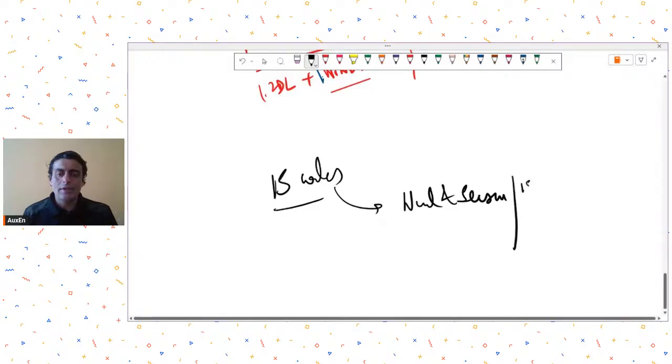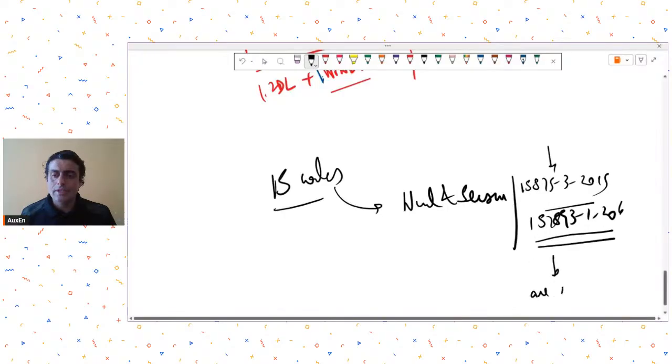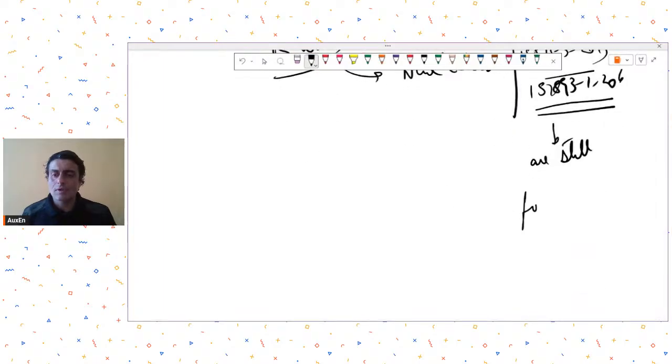So they will use IS 875 part 3, or they will use IS 1893. So they will take the wind and seismic from these. Now the wind and seismic magnitudes for these codes are still for lower return periods.